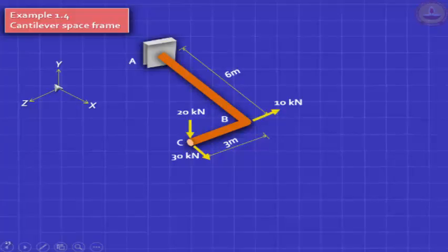Look at this. I've got three axes. X axis is aligned along the shaft. Y axis is vertical. Z axis is along this part of the cantilever. Please note, whenever you draw axes like this in Cartesian space, you have to satisfy the vector rule: i cross j is equal to k. So x pointing this way, y pointing this way, right hand corkscrew rule, z has to point this way. So you should not put z the other way.